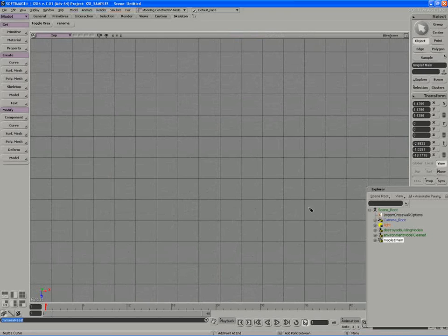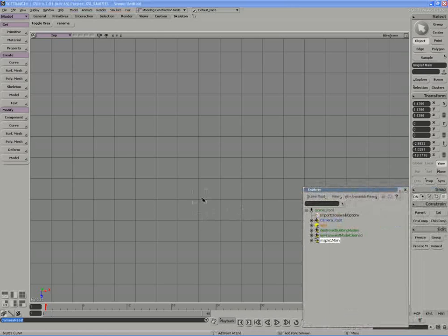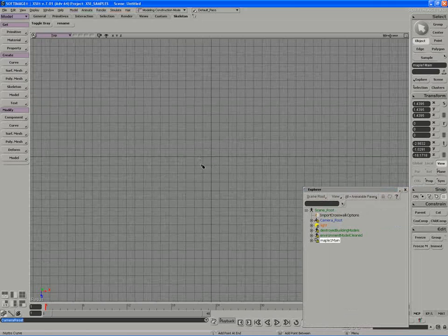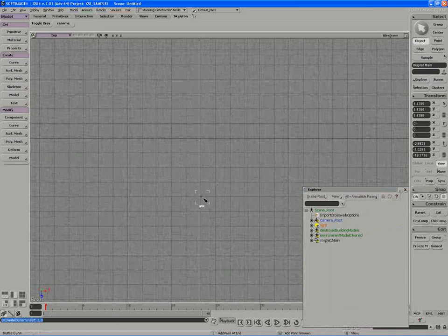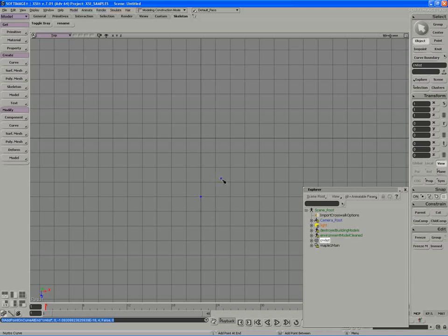I'll start by holding down Control. If I move my Explorer out of the way here and press Control, we activate grid snapping. And if I can figure out where my origin is, here it is, the darker black line. I'll press Control to snap to the grid, and then begin building my curve that will represent the outer profile